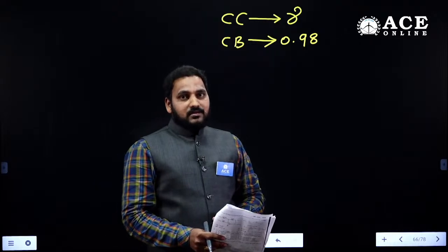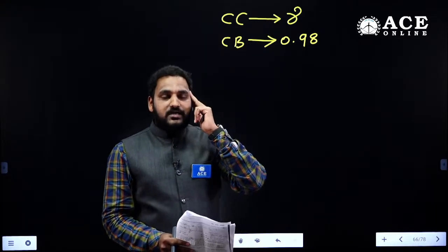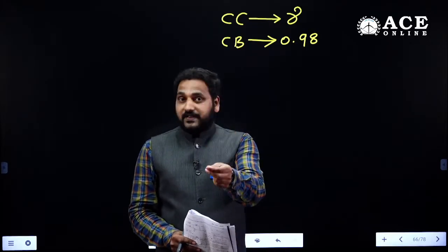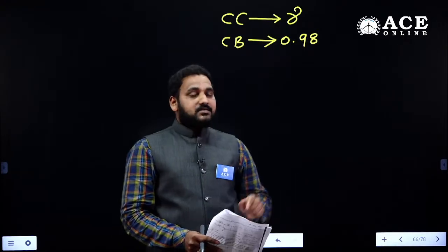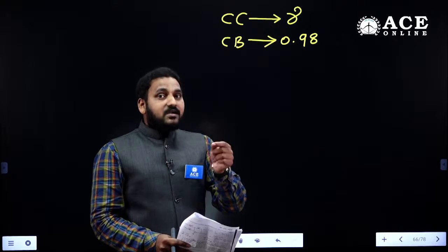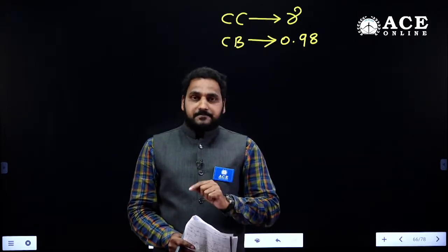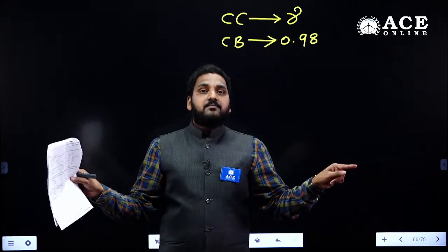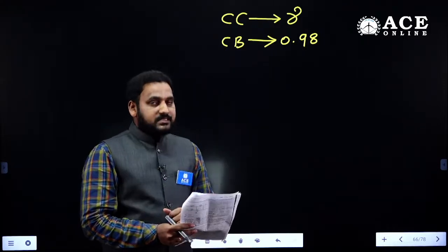And one more important point here is, simply saying current gain, by default students will take beta. No, not like that. The current amplification factor or current gain is different for different configurations of the same transistor. Only if it is in common emitter configuration do we consider the current gain as beta. So I think you may get this point from table number 2 in our notes, table number 2 in transistor biasing, right?